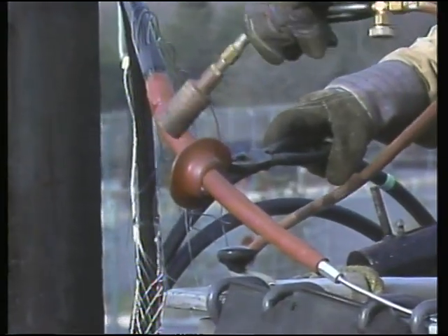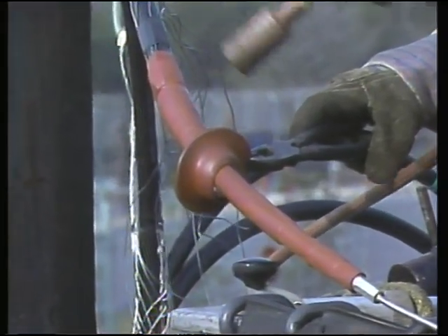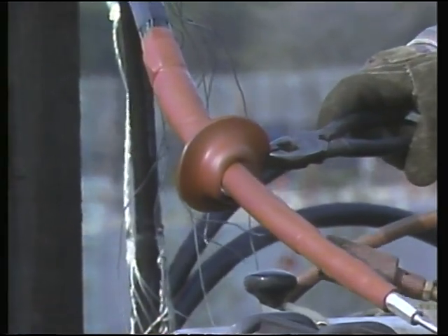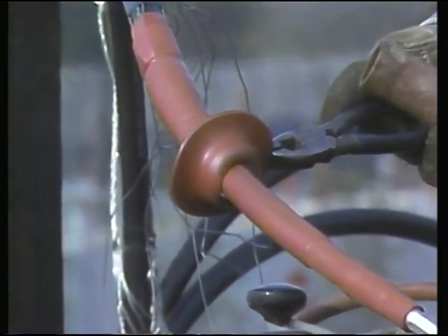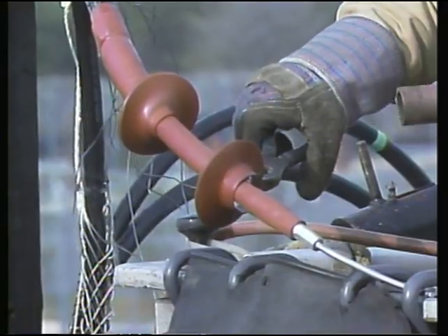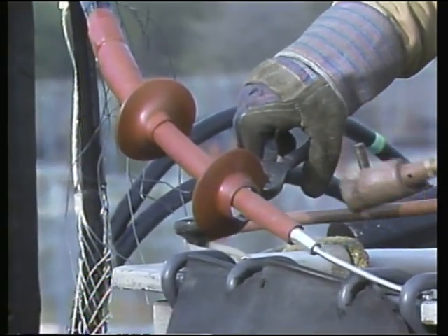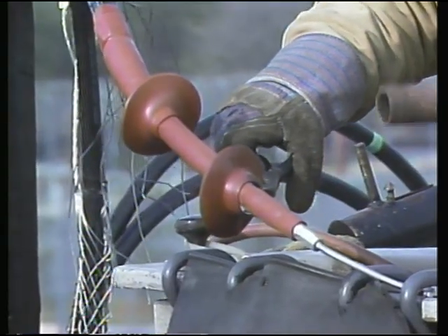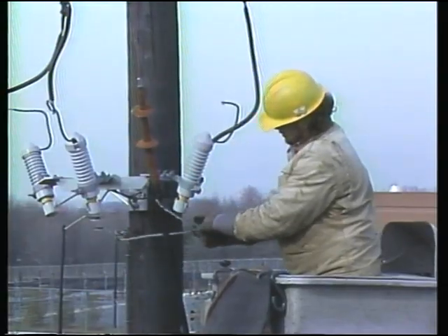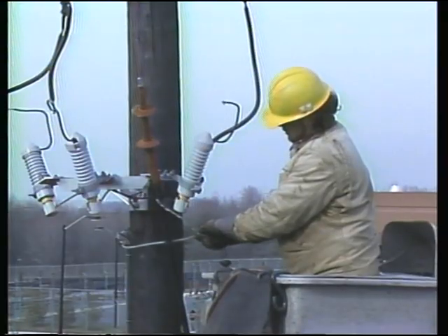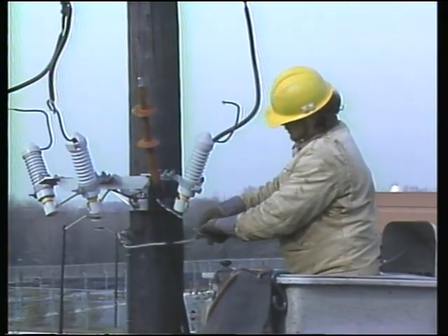To increase the insulation externally and to guard against tracking, the workman installs heat shrink insulation skirts over the tubes. The positioning and number of skirts will vary depending on the voltage that will be applied to the cable conductor. When the skirts are in place, the workman completes the termination by grounding the cable's metallic shield.